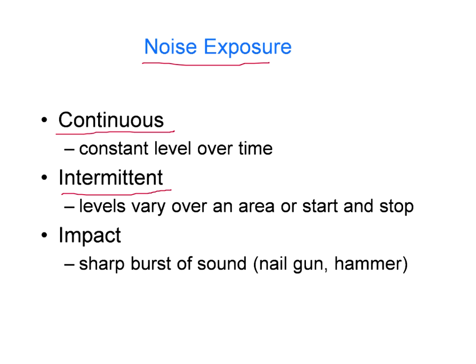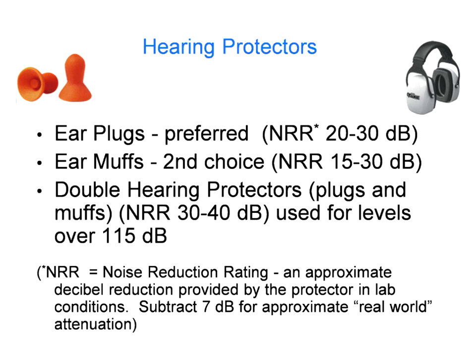Now, noise exposures: continuous exposure, intermittent exposure, impact. Impact means suddenly some sound will come. Intermittent means sometimes it comes, again after 5 minutes the sound will come, again after 5 minutes. Continuous means the sound keeps on coming continuously for the whole shift, 8-hour working shifts. So these are the types of noise exposure in a working area.